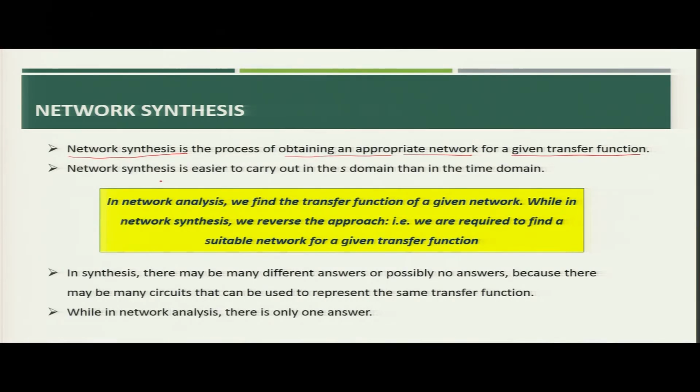Now, network synthesis is just the opposite of network analysis, where we get the circuit and try to find out the transfer function of the given circuit. Network synthesis is easier to carry out in the S domain than in the time domain. So, in network analysis we find the transfer function of a given network, while in network synthesis we reverse the approach. That means we are required to find a suitable network for a given transfer function.